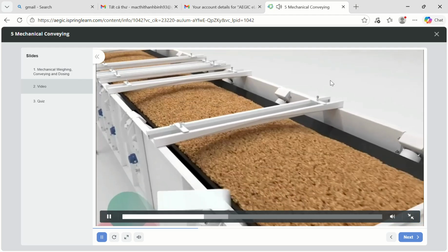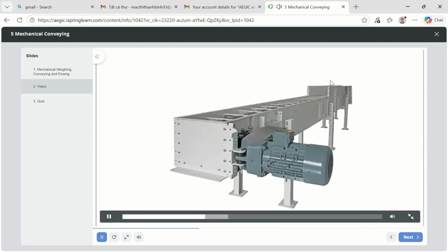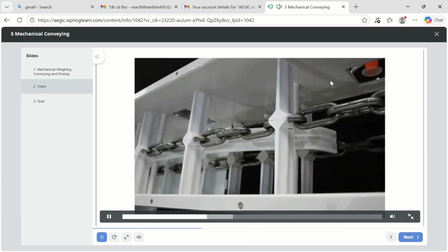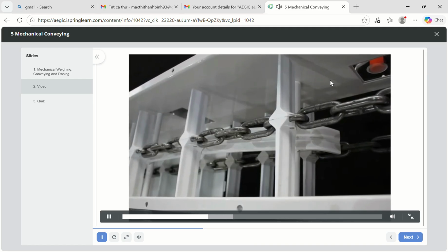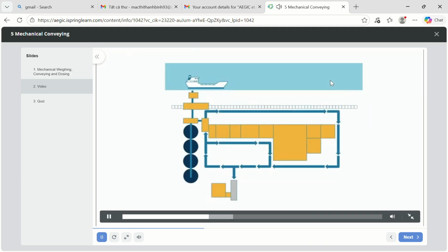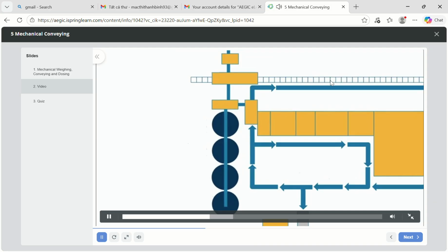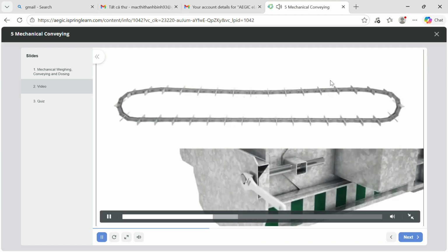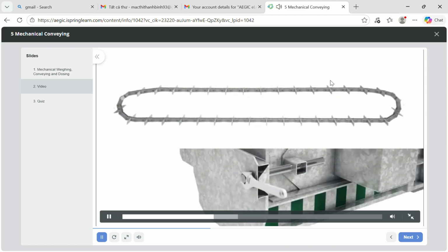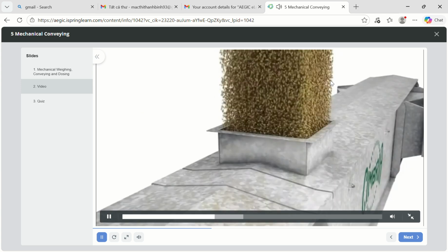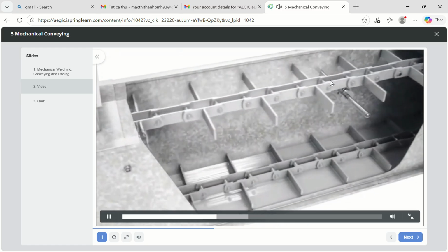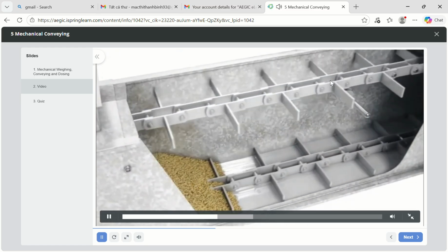Chain and belt conveyors are generally used for conveying grain horizontally over long distances where a high capacity is required. For example, moving grain from an intake point to the silo elevators. A belt or series of links in a chain form a continuous loop. The chain or belt carries the grain in one direction and drops the grain at the destination. The empty belt or chain then cycles back in the other direction.